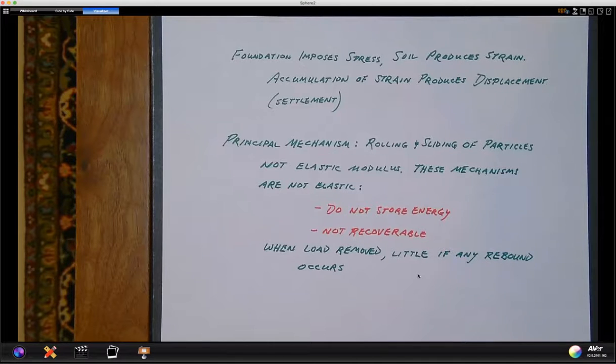And for that matter, we understand at this stage of the course that foundations are oftentimes embedded under the ground surface, and you actually need to account for that. And you would modify your dimensions accordingly, such that when you utilize the charts, you're talking about distance below the loaded area. In other words, distance below the base of foundation would be what it is.